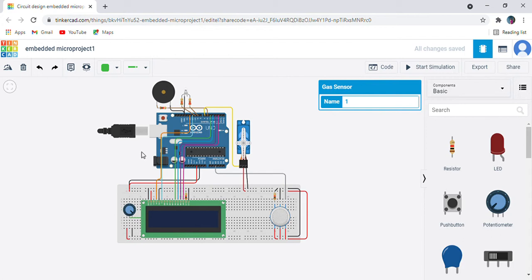The Arduino sketch reads sensor data from the MQ2 gas sensor, compares the sensor value, displays sensor data on a character LCD, invokes an alarm through an LED, and operates a DC motor in response to intense smoke by automatically opening the ventilation in the home for reducing the spread of gas.